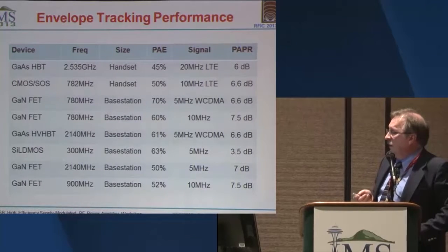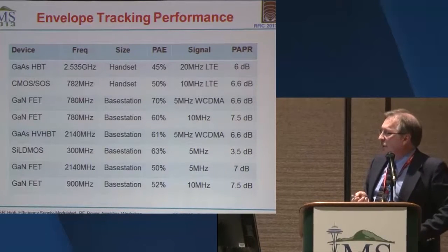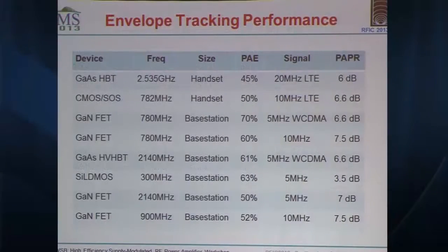On the one end, we've actually applied it even to millimeter wave, but one of the issues with the millimeter wave and some of the other specialized cases that we've done is we didn't resize the supply modulator to that particular application. And without resizing the supply modulator to that particular target output power, the numbers don't look quite as impressive. But we realized that if we were to redesign the envelope amplifier for that size, the RF PA is operating very efficiently, and there is a very nice solution space there. So being able to do these on the fly for the different sizes would be phenomenal.